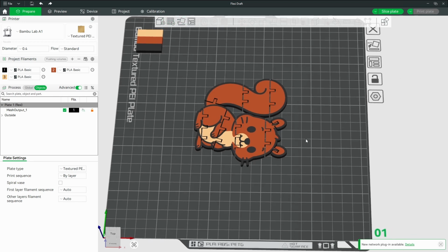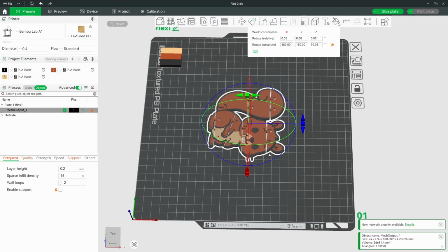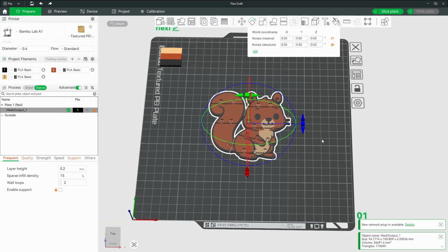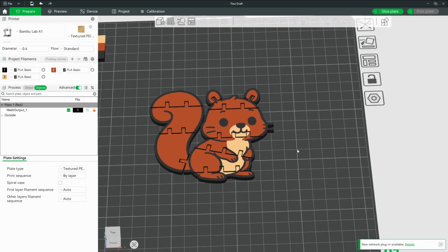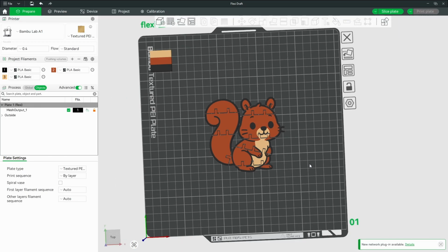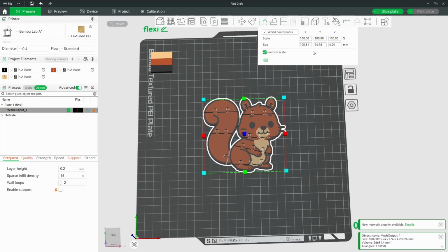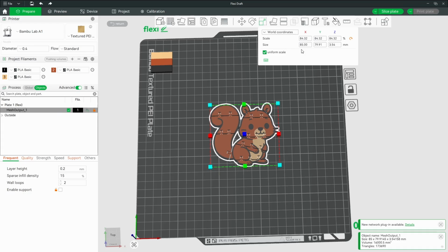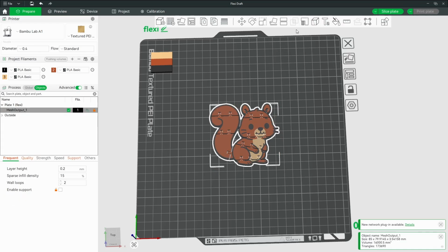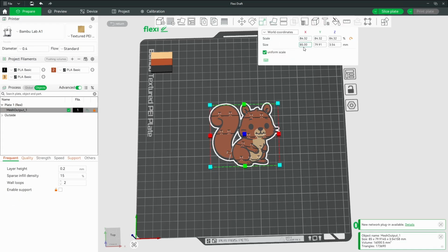You know I have a thing with orientation, so I'm going to have to grab it. I'm going to change it to this direction, and there we go. We've got our little model on our build plate. The size, I don't know if I'm gonna want it at this size. Let's see, it's about 100. I might do smaller. I like some small flexis. I think smaller flexis are pretty fun to play with, so I'll do 85 at the max. I did that by hitting the scale button right here, guys. At the x-axis, the biggest axis, I put 85. I'm going to try that.